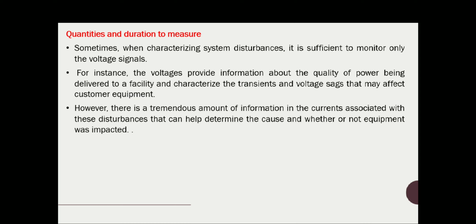By measuring the voltage, you will get some information, but there is more information you can gather when you are monitoring the current waveform. You can determine the cause of the power quality issues and whether the equipment will be impacted, and how much it is impacted, if you are measuring the current waveforms.